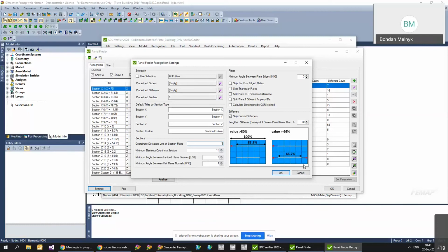Yeah, this is a very important feature because for those who model ships, the stiffeners were not directly touching the other sections or longitudinals or girders, and it was a problem because then you had to create some dummy elements, or define manually how to split, or do some extra work if your stiffeners were not completely 100% length from node to node.